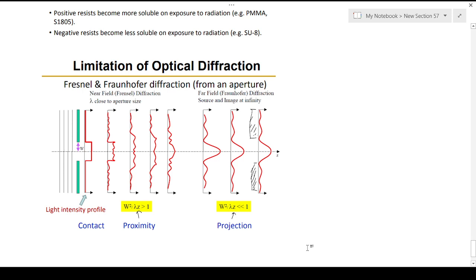Okay, and it will be focused by utilizing a converging lens, right? So it is much the better technique, because in the proximity case, the frontal case, the patterns and UV radiation and everything will be very adjacent to each other, nearly placed together. So it is difficult to produce a proper intensity profile corresponding to the image. So that is one of the problems.